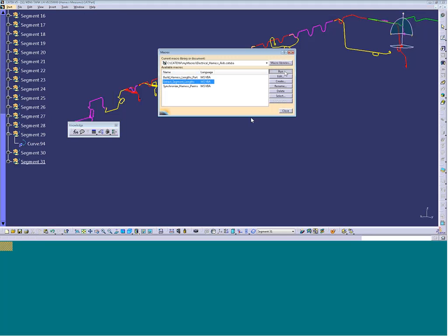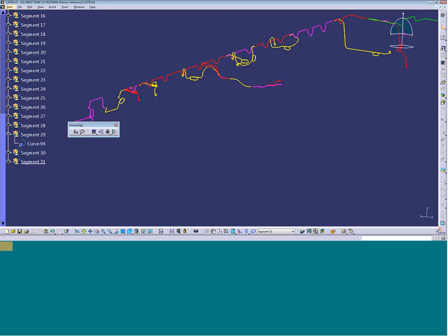So if I run this, this program now does a number of things while it's processing. It's going down and looking through this well-defined structure of segments in the wire harness. It's grabbing the geometry in each one of those segments, and then it's producing an output in an Excel spreadsheet, which is the way they wanted this displayed, which gives them, based on each segment, what the length of that segment is in inches and in millimeters. So depending on their customer requirements, they could go with one or the other.